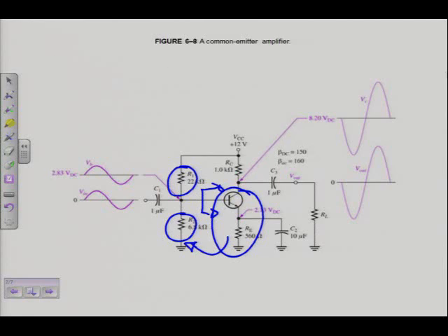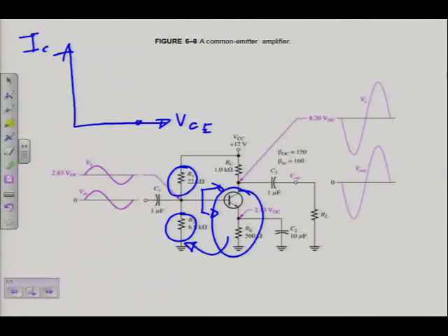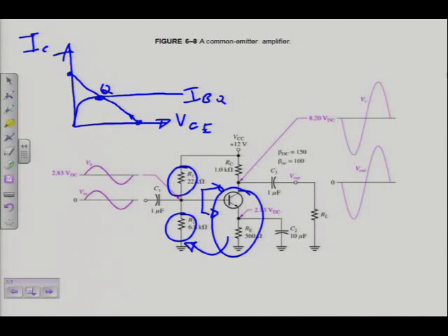Why am I so serious about getting the voltage that I should? Because the first thing that we've learned is the transistor's characteristic curve, IC versus VCE. I've got my load line, and we saw that if I want to bias using R1, R2 to get my Q point in the middle of the load line there, that IBQ is determined by what? VB, voltage determined by R1 and R2.